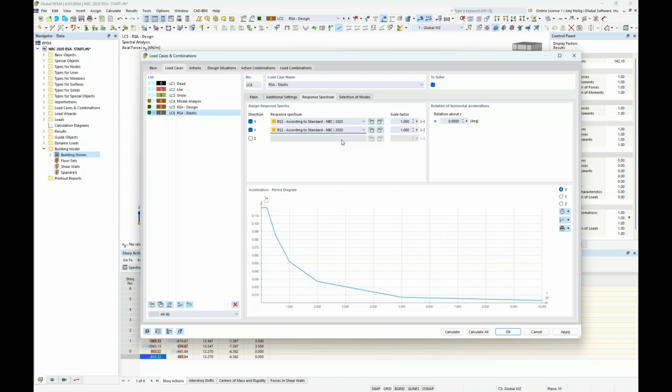We would take a look at the building model results, and in particular, the drift, to make sure that our drift is limited to what Article 418.13 has set forth. No need to run that calculation now. It's really the exact same workflow. I just wanted to show you how we can essentially consider that elastic response spectrum analysis.